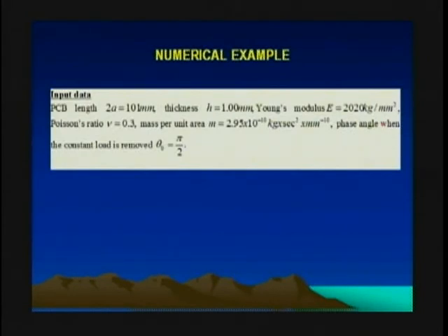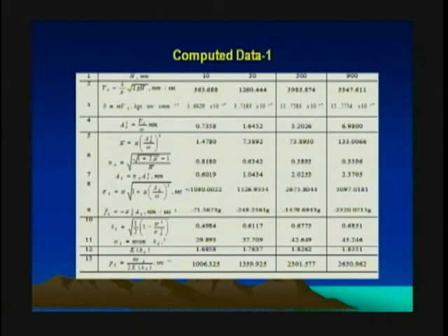And here the numerical example was carried out for a printed circuit board with its dimension 2A, thickness 1 millimeter, so the board that we already used. And here you can see we calculated the data for the situation when the board is dropped from different heights. We start with 10 millimeters, 50 millimeters, 500 millimeters, and 900 millimeters, which is the standard. But even long before we reach this 900, the standard, we see that the nonlinearity has a significant effect on the results.